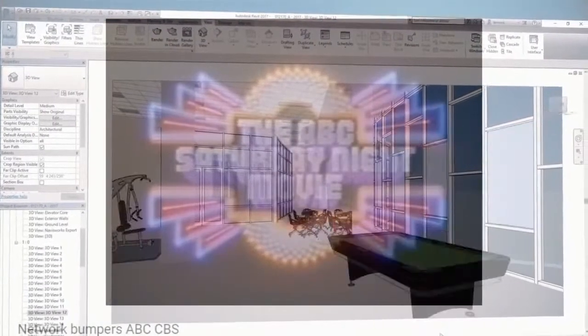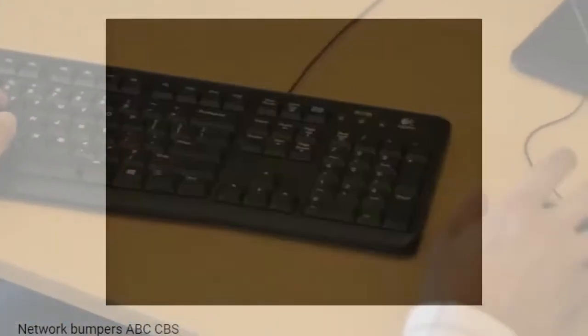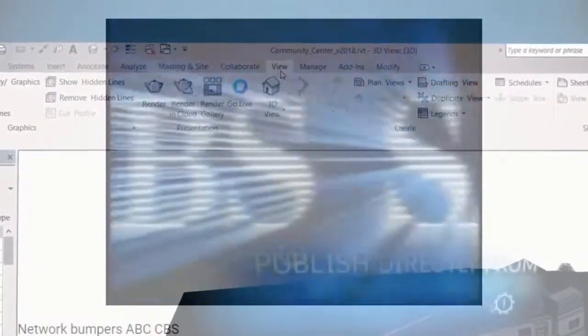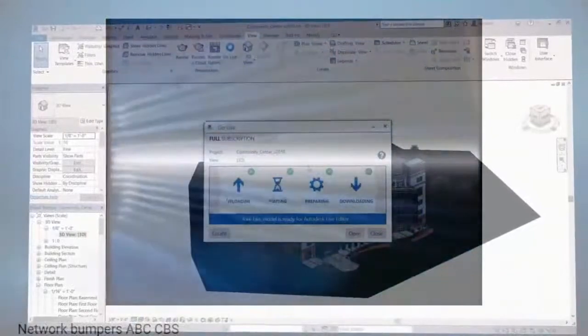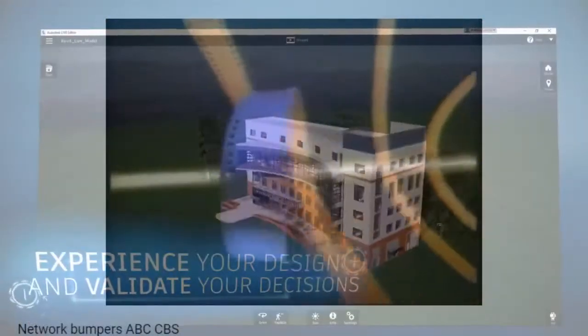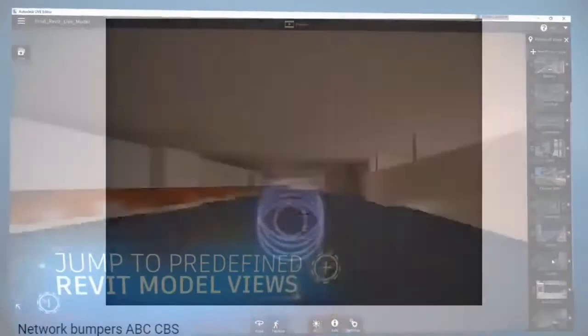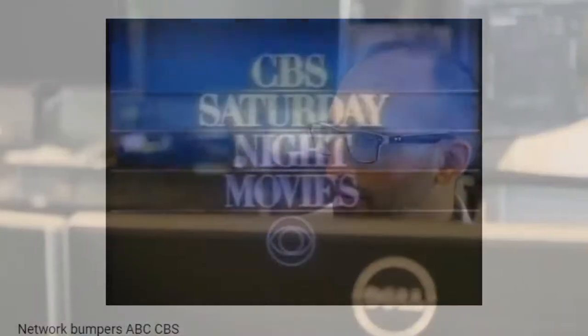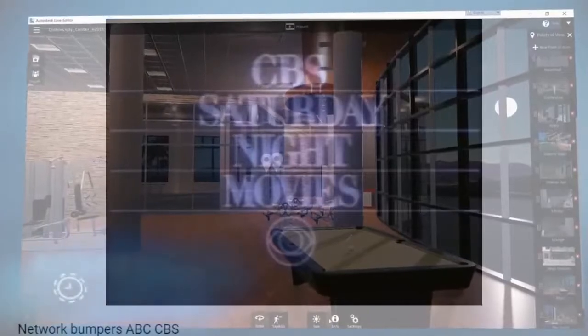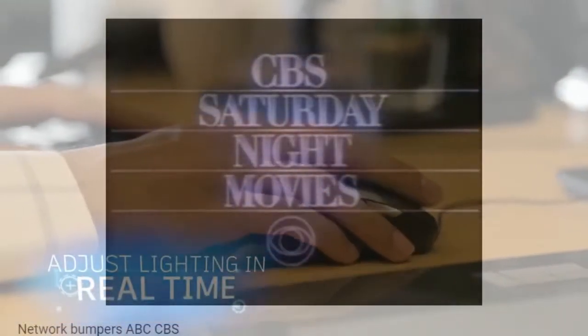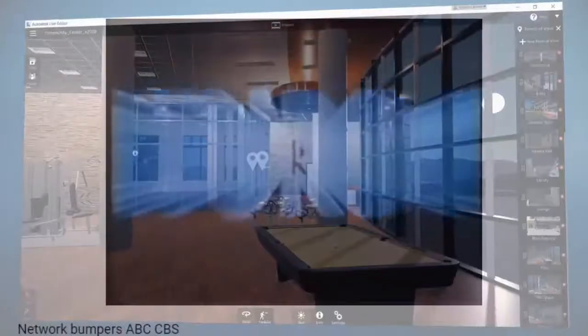Let's just make sure we have this all set up so we can see it in our views. We have a section, longitudinal section. Let's draw another section right over here. Let's drag the back plane, far cutting plane, a little closer, right there. Alright, so it says we can create an in-place floor, right? Architecture, Model in Place, Floor, right? So we can get into the family editor. Let's leave this as Floors, Floor.